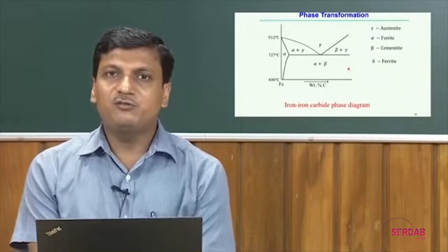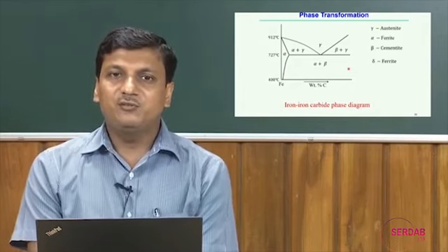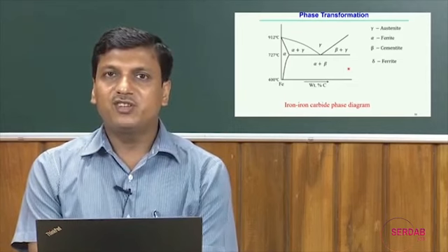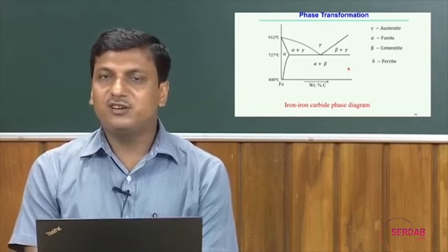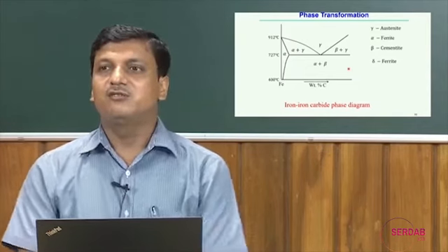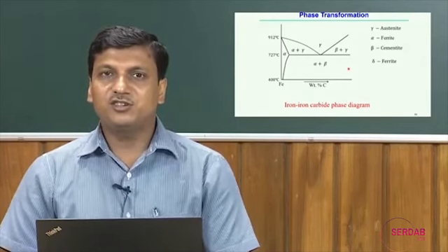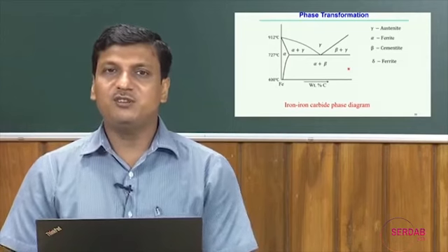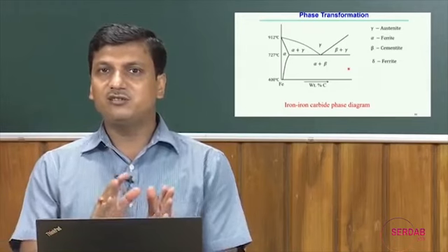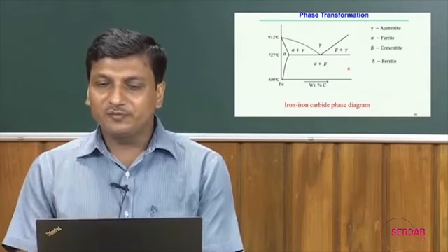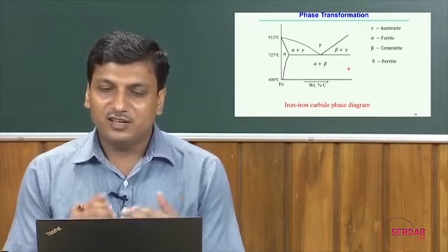So, if we know the phase diagram for a specific binary alloy system, we will be able to find out the coexistence of a single phase or a mixture of two different phases over the temperature range. We will get all kinds of information from this phase diagram. But note that this is an equilibrium phase diagram, and it is no longer related to the time component. Therefore, the rate of cooling has no importance here.